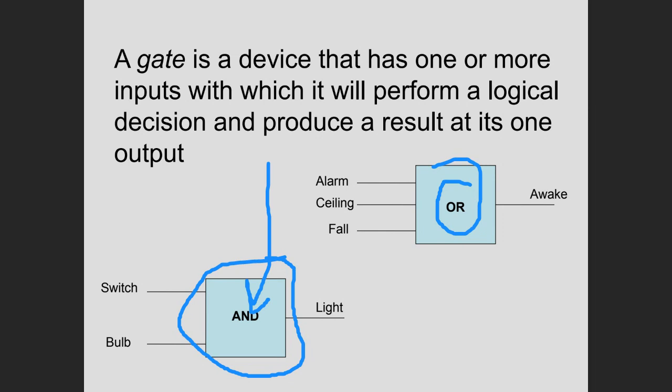And we mentioned transistors when we classified PLC outputs. If you remember, there was a transistor, triac, and relay. Well, a transistor is just a special kind of switch, a solid state switch. Thing is, we can make these devices really tiny and put literally millions, and in some cases billions, of these little switches on a really small area. So the world is kind of built on these silicon chips. Without getting too detailed, you can use these transistors to implement those switches in series for the AND, or the switches in parallel for the OR, really any logical function.